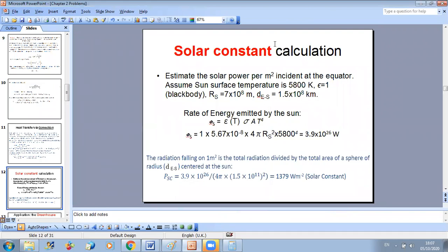Oh, Ibrahim, if we have a phase change of water, of course it will be different. If you have a change of phase during the convective process, then you will not deal with sensible heat, you will deal with latent heat. Whenever you have a mixture, instead of the convective heat being transformed into sensible heat, it will be transformed into latent heat.